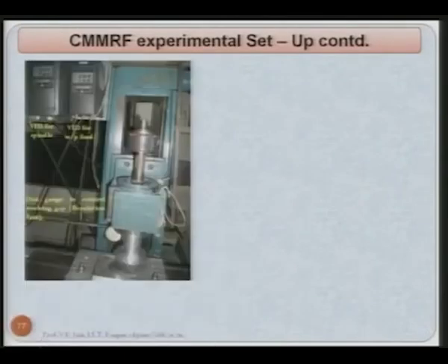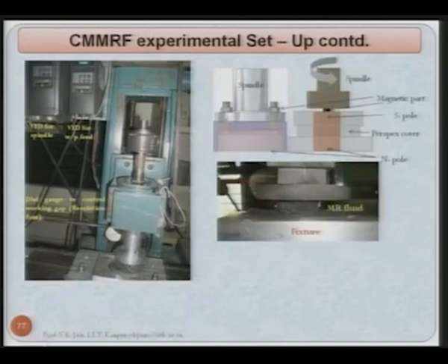This is the experimental setup which was developed and you can clearly see that these are the VFD variable frequency drives, 2 variable frequency drive, and here the dial gauge to control the working gap between the top surface of the workpiece and bottom surface of the magnet. Now, this you can clearly see, here is the workpiece and this is the brush MR polishing fluid which is forming the brush, and this is the one which is really responsible for finishing.